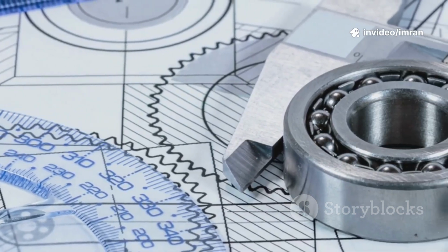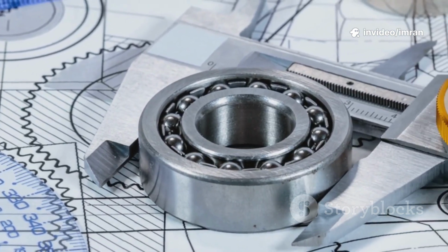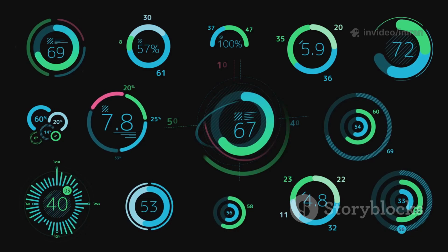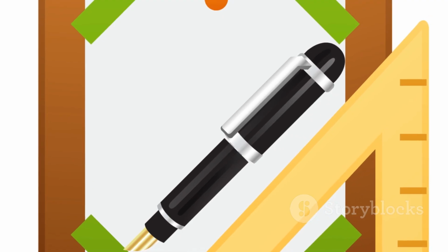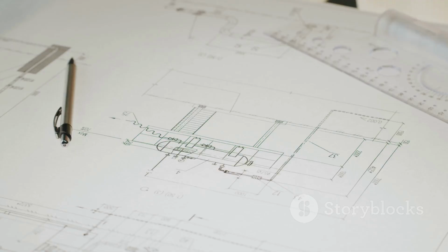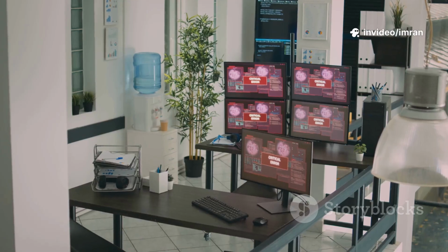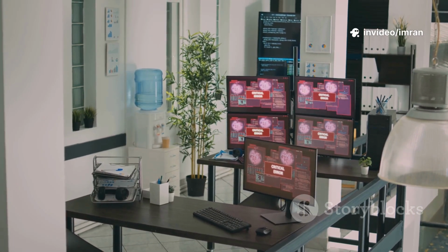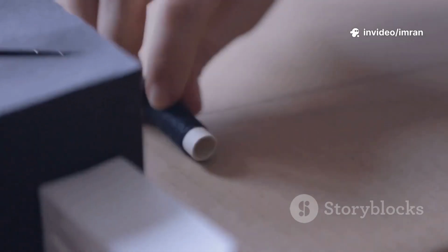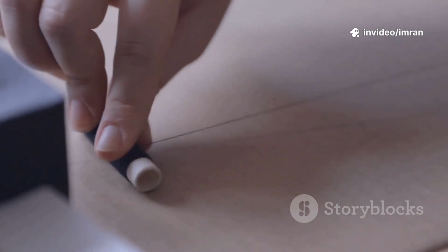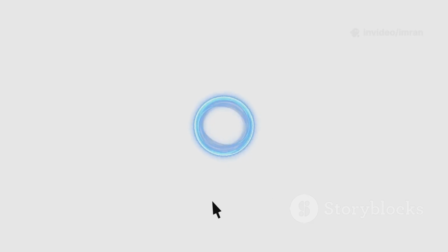Circles are essential in designs, from mechanical drawings to architectural plans. The circle command offers several methods. Click the circle icon or type C and press enter. The default is center radius. Click to define the center, then specify the radius visually or numerically. Alternatively, use the diameter option by typing D. Explore other methods like 2-point, 3-point, and tan radius for different geometric problems.